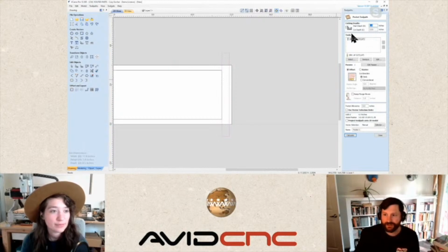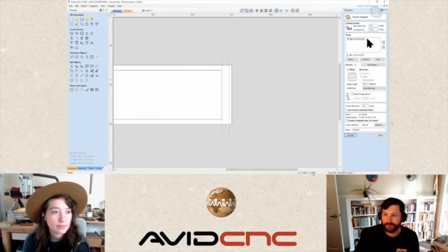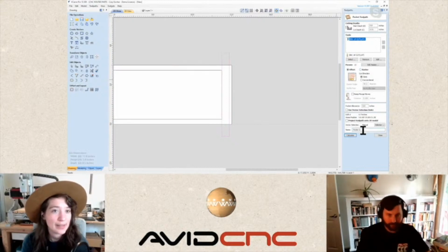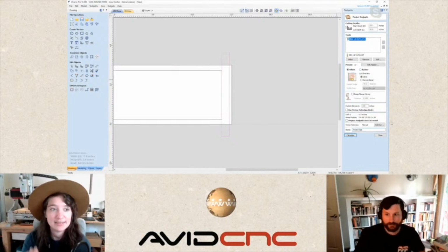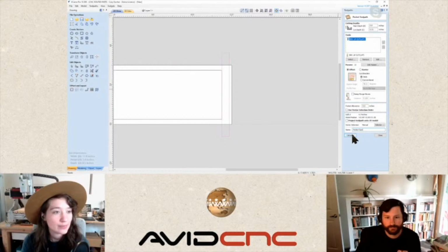We are going to go to a total depth of 0.51. This has us going in 13 passes. We are going to use an offset toolpath, Sami, in this instance. Would you use? Yeah, I would. And then you can select climb or conventional here and make sure that when it's coming up against your final workpiece, we're getting that climb cut.